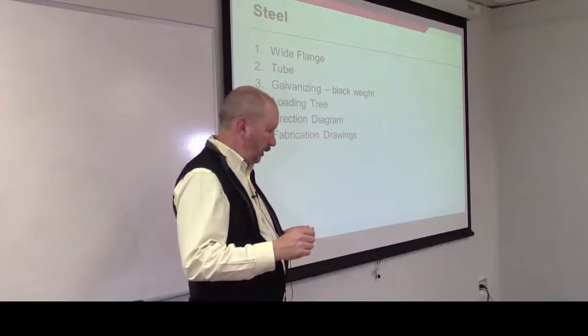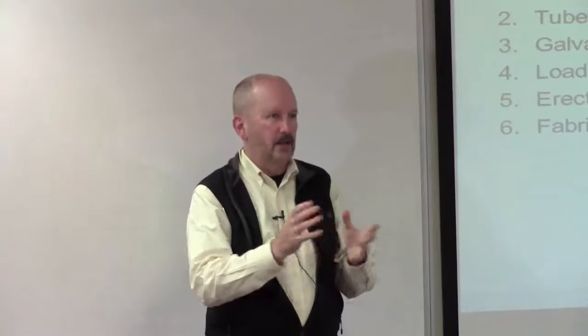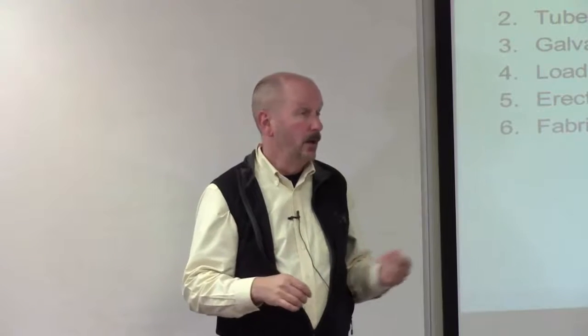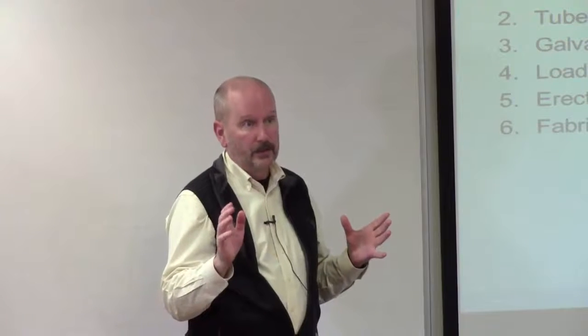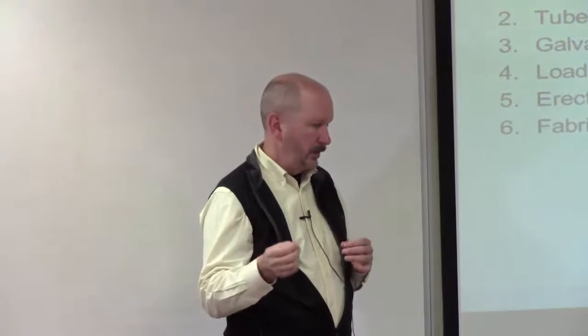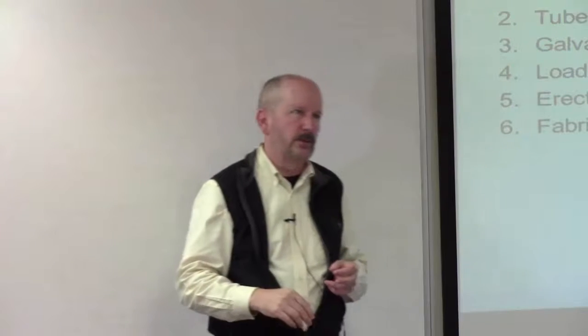All right. What information do you, as the electrical designer, have to tell your civil structural brethren so they can design your structure for you? Well, first thing, you want to give them a plan and elevation so they can see the general shape of whatever it is that they've got to build. And you also need to give them a loading tree. You've got to tell them what you're going to mount on that structure. A good example being disconnect switches.